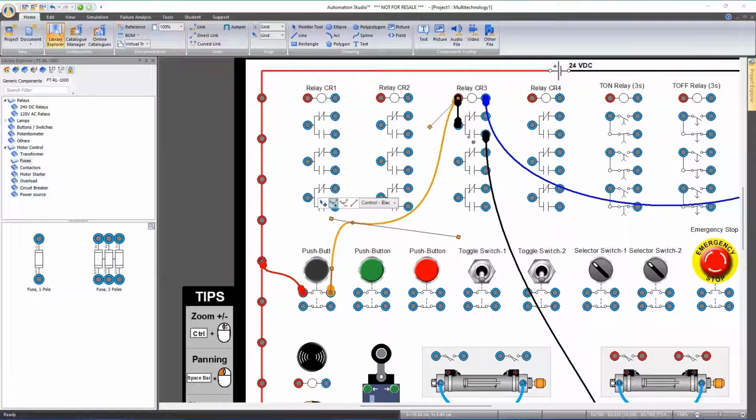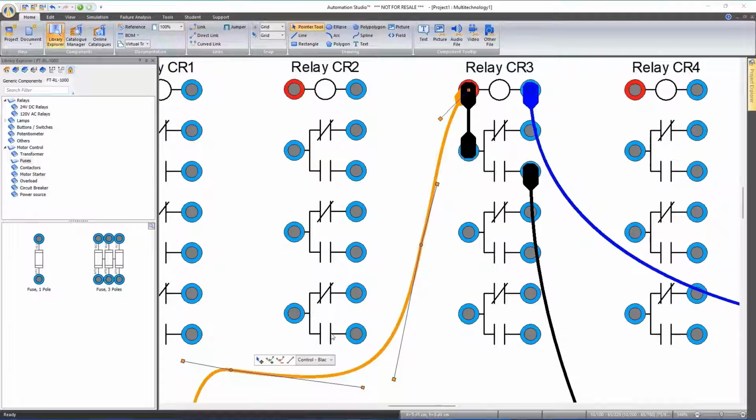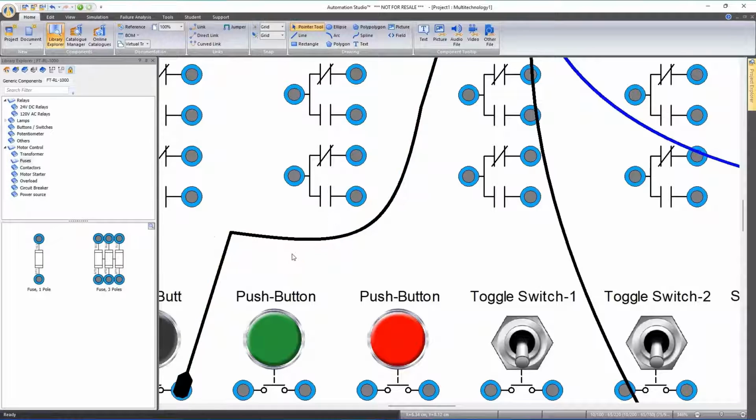Okay, so there's a way that you can add some sections like this, which allows you to make more adjustments on your line. And let's say you say, you know what, Chris, I want this line here to be straight for any reason, this portion of the line. You click on it, you go here, straight line, and you click on this segment, and you see it became straight. If I click on this one just to show you, it becomes straight also. Okay, so this may be something that you may need.